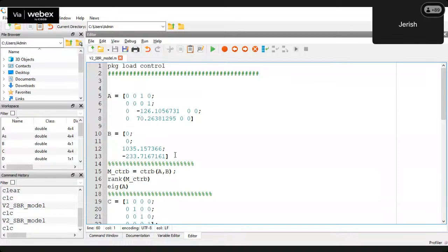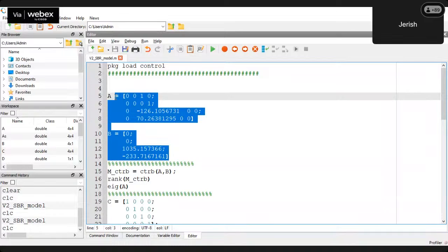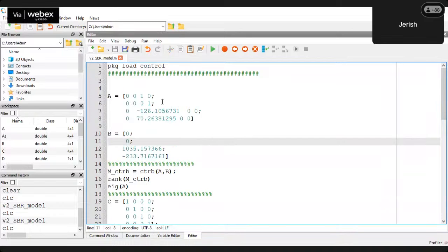So this is how the A and B matrices would look, where there are zero terms corresponding to the zero values in the Jacobian for A and B, and the calculated values of k1, k2, all the constants. Now, we saw that there's a controllability matrix which tells us whether the system is controllable or not by assessing the rank of the controllability matrix.